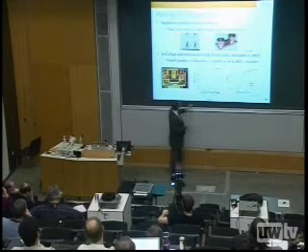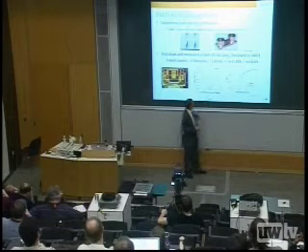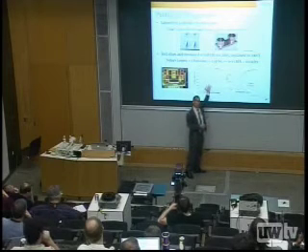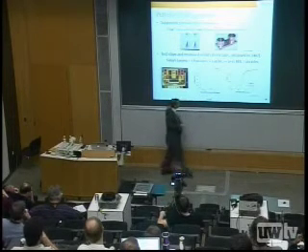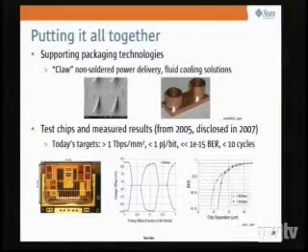This is a contour plot of the eye diagram at a certain bit error rate. I think this is 10 to the negative 12th, I'm not sure. You can see that the eye width is relatively good, about half a UI, with a few hundred millivolts of voltage margin. That's reasonable. What I like about this plot is the bit error rate as a function of chip separation. If the chips are really close together, under about 8 to 9 microns, we see no errors. As we move them apart, we start to see errors because we're losing focus. And if we go out to 12 microns, it goes to hell in a handbasket because you just can't communicate over that distance.